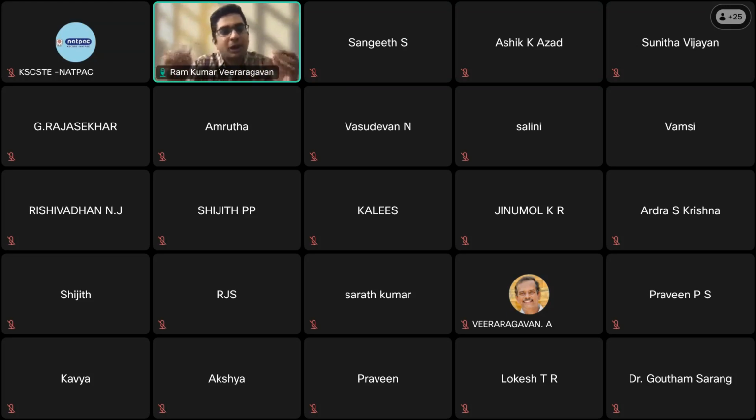You can't get a completely balanced mix design. So you have to have a minimum criteria, like, I need to satisfy a minimum cracking threshold as well as a minimum rutting threshold. If it satisfies these two minimum criteria, then I'm good. And to achieve that, you have to modify your specifications based on your need, based on the agency's need.